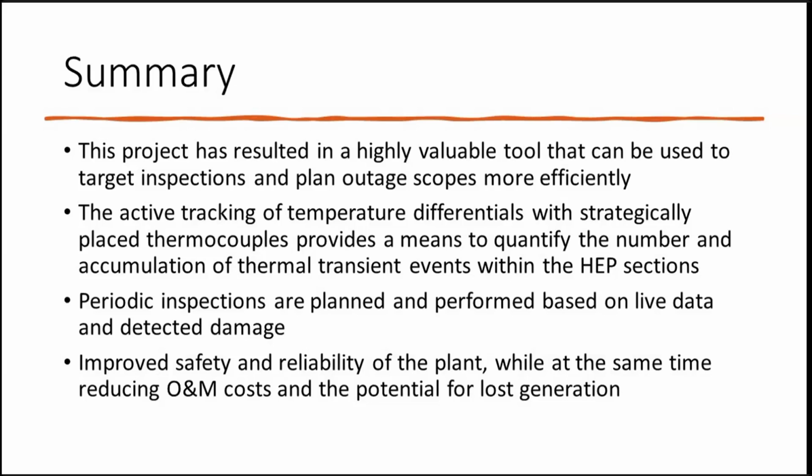We just used type K thermocouple wire that has a fiberglass sheath with a stainless steel outer braid, and it's made to withstand the high temperatures you'll see in an HRSG. I think it's rated for up to 1300 or 1400 degrees, and it does well. As long as you attach it properly and leave a little bit of room for thermal expansion, it's going to last you many years. Yeah, Julio, if you want to drop me an email or send a message through Scott, I can send you those details.